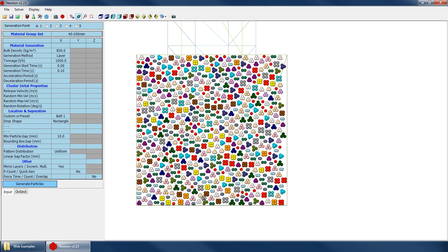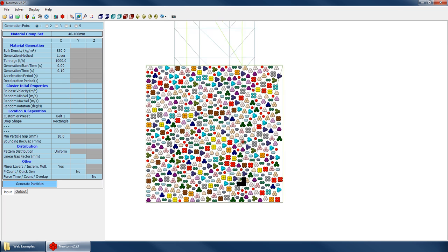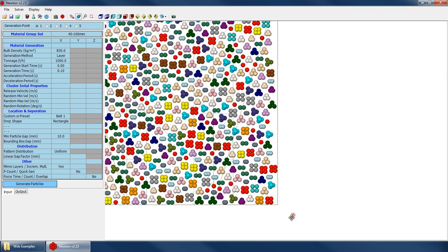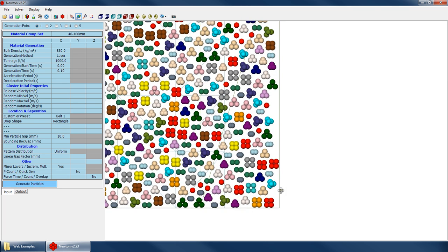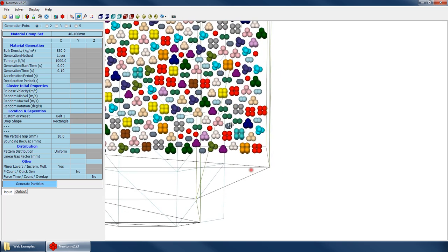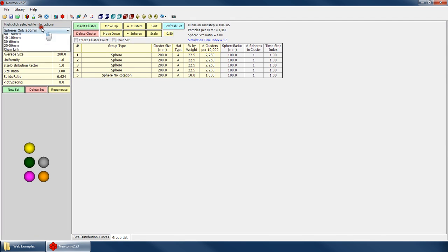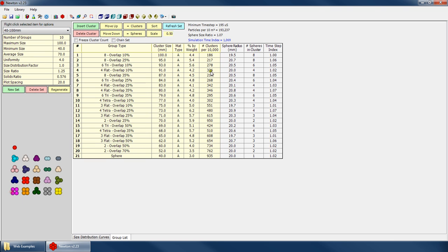So what happens is we get to this very last row, and we're starting to put particles in, and then we move over a little bit, and the first time where we see, oh, I can no longer fit a cluster here because I'm hitting this wall, we force ourselves to start a new layer. So this is almost kind of unfinished, because maybe my next particle I wanted to generate right here was this teal 8 cluster. Maybe I wanted to stick that cluster right here, but I couldn't fit it. So Newton looks at our particle library and says, well, this 8 cluster, I need to have